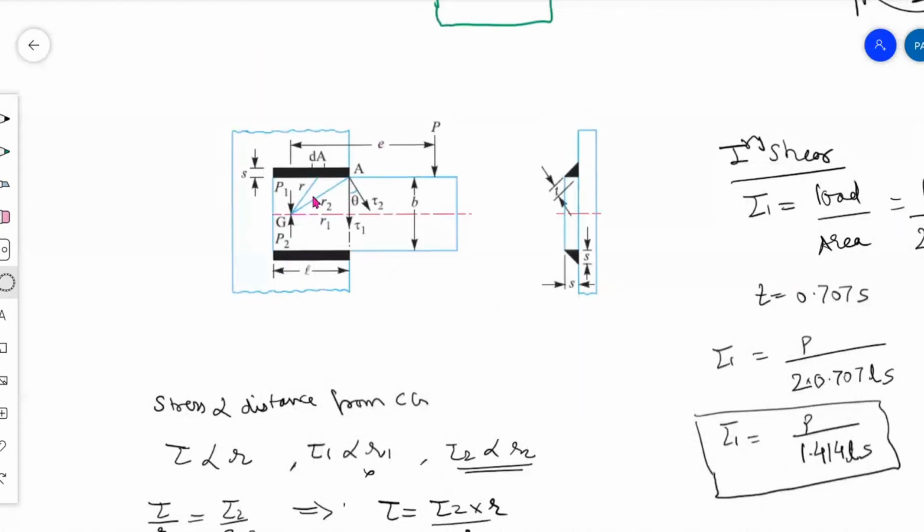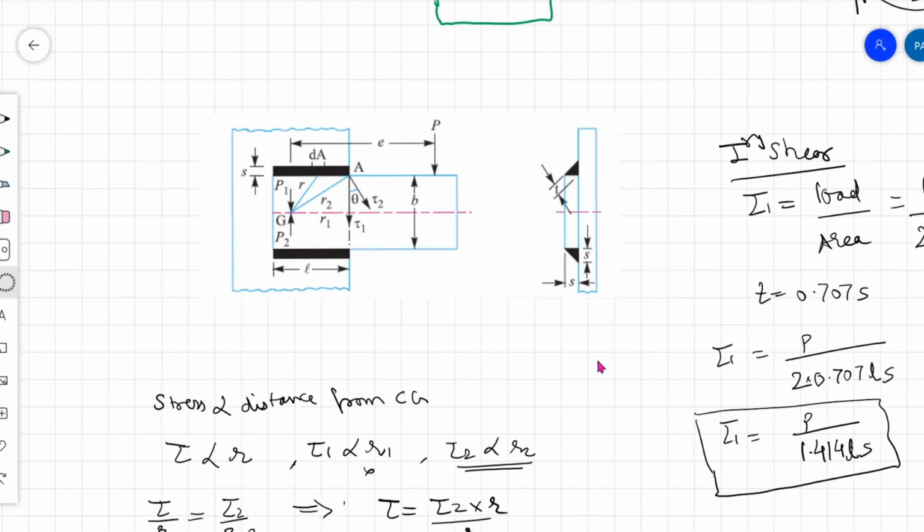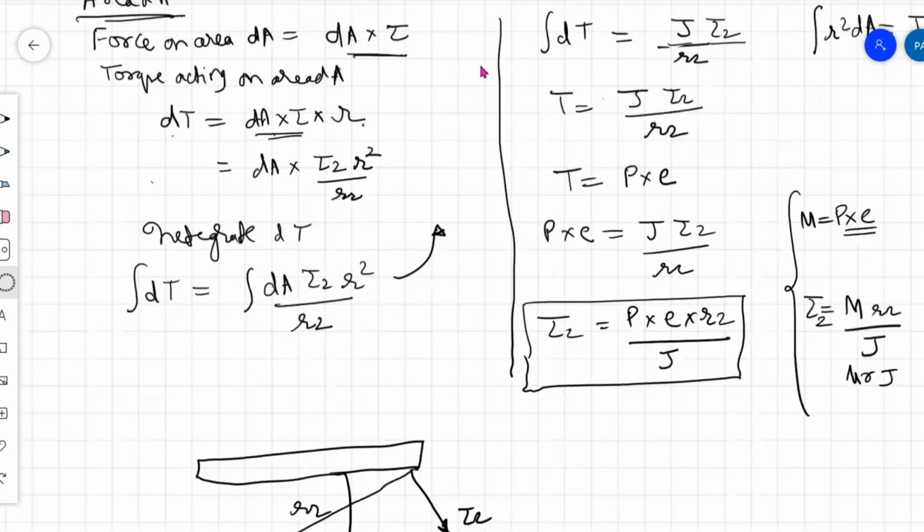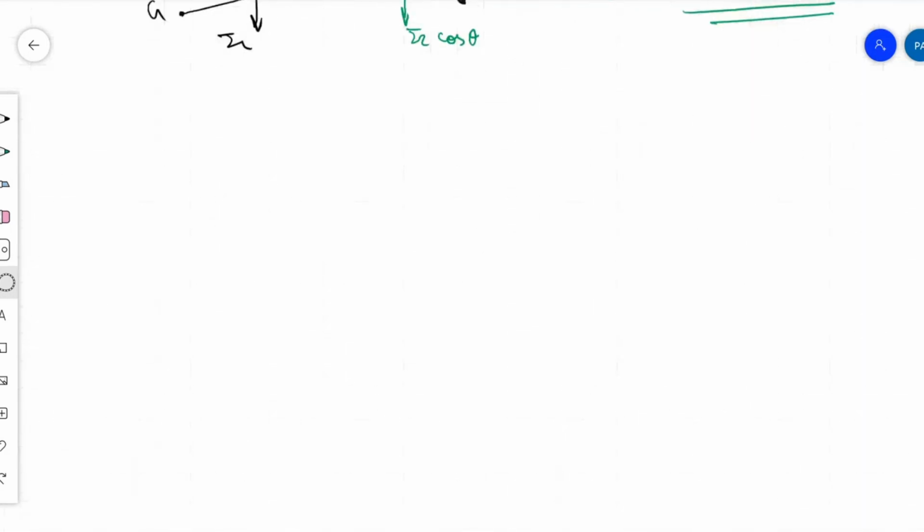This is the sketch where there is something called as R2. R2 is the distance of the farthest end from the CG of the weld system. The first step is to find CG of the weld system, and then from that we can find the other values. So we'll see today how to solve a sum on this by practically implementing this thing.